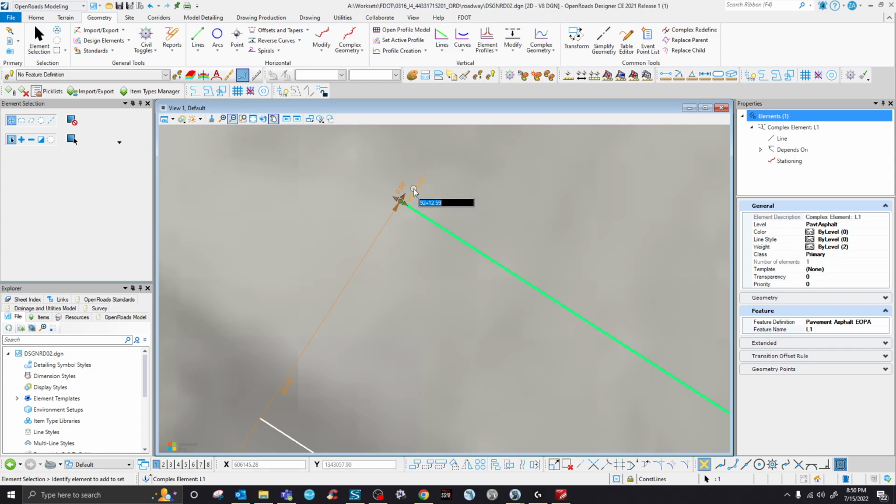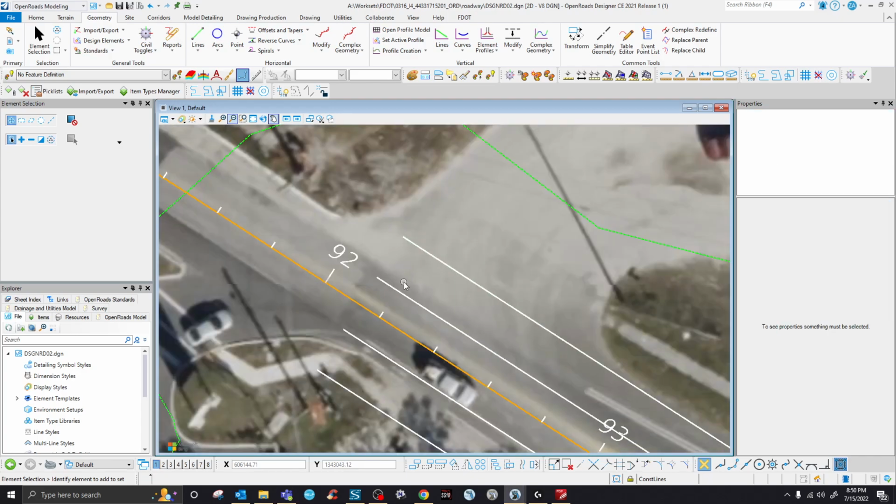If you want to be lazy, just click on it like this and do a copy, so you do not have to write it again. And then come here to modify. Why am I talking like this? Anyway, I wanted to start at 0, force it to 0, and then paste the station. Click enter. Make sure it is there, and that's it. And then without even exiting, let's do the other ones too. See, start at 0, same station. And then this, start at 0, same station.